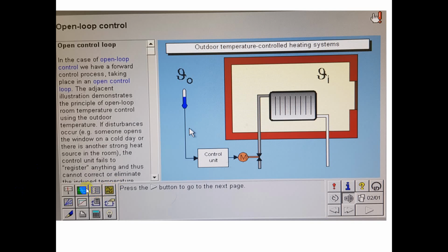The next thing which we are going to use is the oscilloscope. Whenever you put something in the Y1 or Y2 channel here, you can view the waveforms by clicking on the oscilloscope here. The next one is your multimeter here. If you place even the mouse on it, it will show you which particular icon, this one. Just click it, you will get the value directly on your software. Similarly, if you want to plot some curves or graphs, you can use the characteristic plotter here. Similarly, this will be for the response. So these are the 5 icons which we are going to use in our control system experiments here.